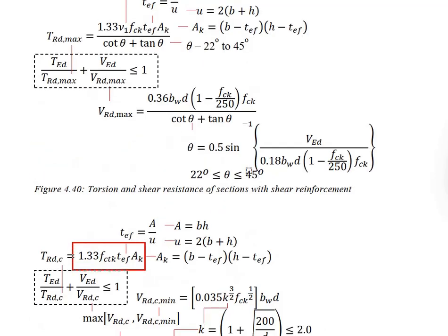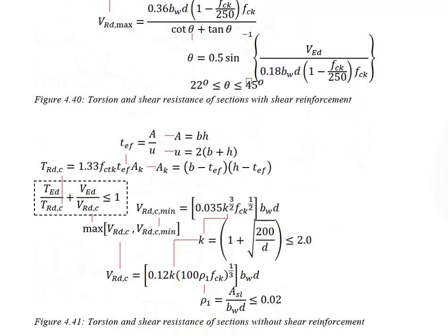You may make a quick comparison in terms of the formula here. The structure of the formulas is similar, except that it does not contain the shear angle. That means you have no compressive strut in this case, as it is not calculated on the strut model.